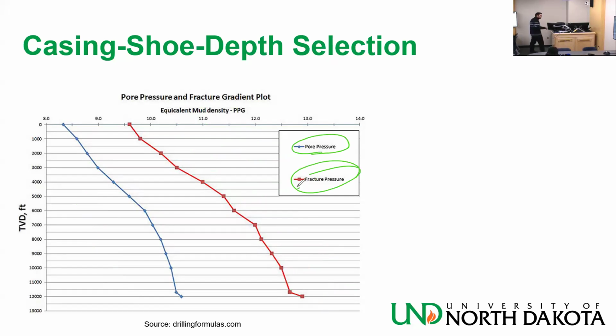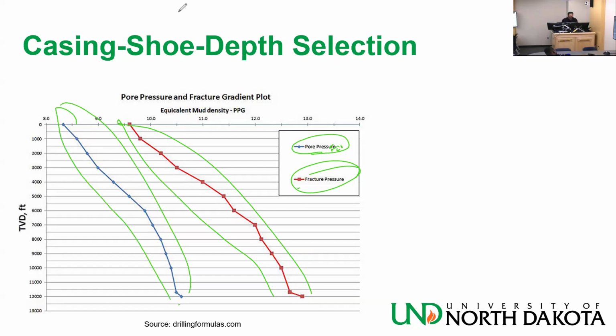And same thing with pore pressure. Sometimes you have breakout pressure, which is a little bit higher than that, and it can still cause damage. So basically, for every line, you have a bunch of different pressures, and for the red line, you choose the smallest one. For the blue line, you use the largest one of this list, let's say.